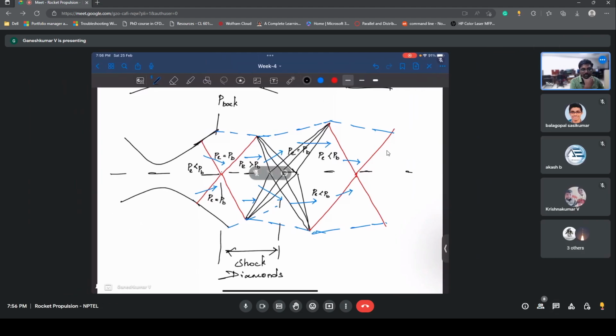Yes, sir. So basically, you can take a compressible flow course, or you can read the book Compressible Flow by John Anderson. Basically, you need to match the pressure, and the information doesn't reach you, so you put a shock wave. You put a shock wave and increase the pressure so that it reaches the back pressure. Upon doing that, it changes the direction of flow, so for the mass it has to put another reflected shock wave, which again makes the pressure greater.